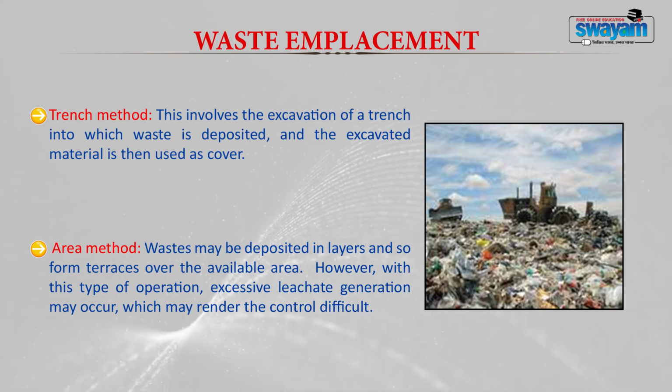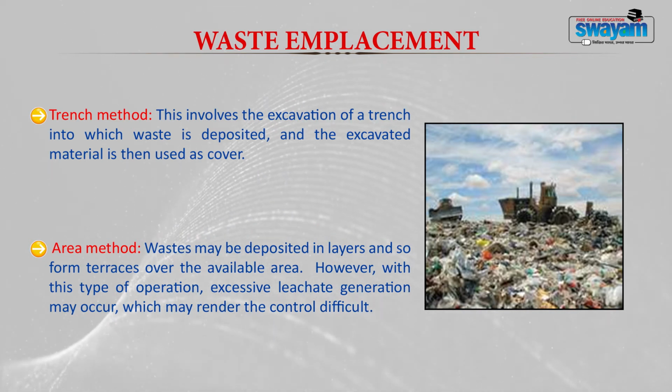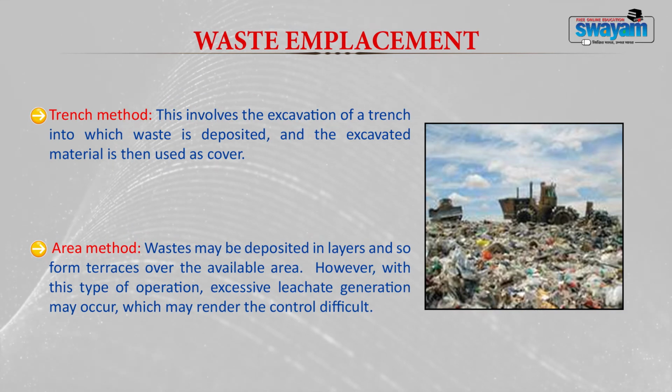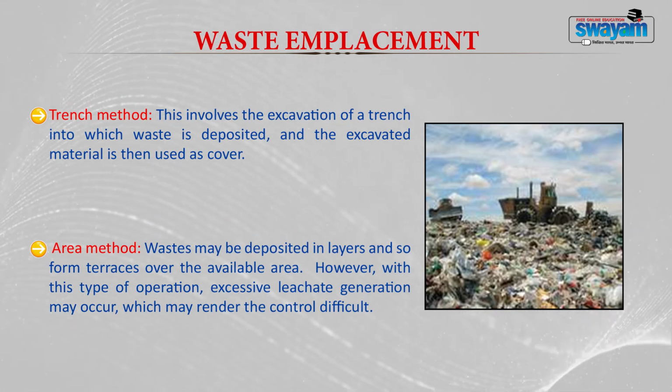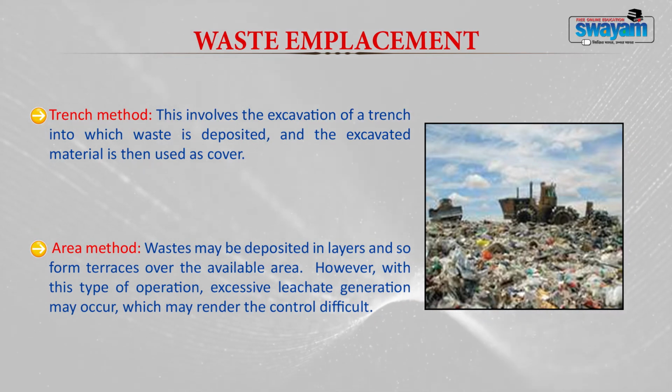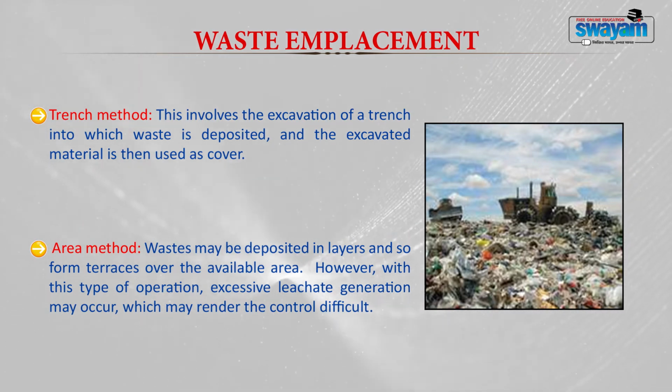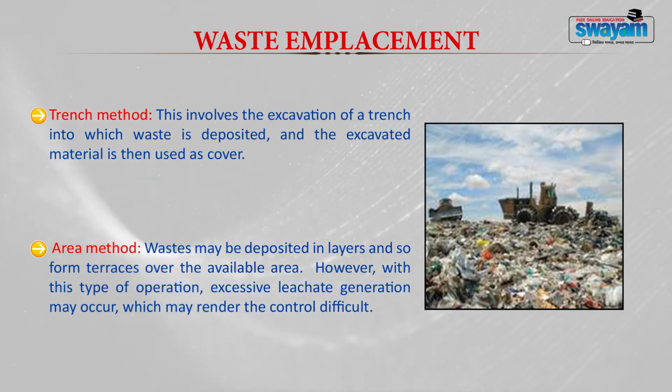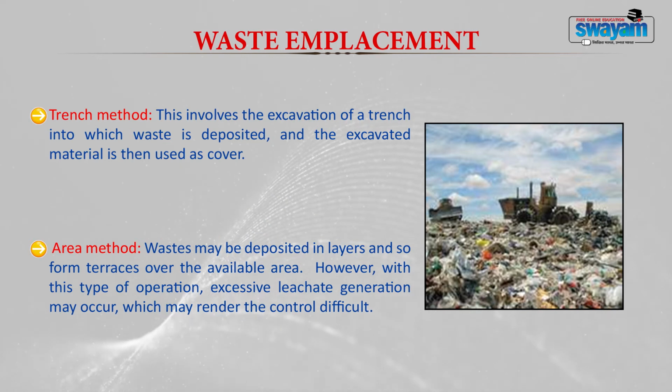For example, here the entire landfill area, the waste that is collected is brought and one uniform layer is made on the landfill area. Once one layer is completed, the next part of waste again will be dumped and covered in an entire area to form the second layer. So, here if you have a cross section, you can see the waste dumped or deposited layer by layer. It also looks like a terrace.